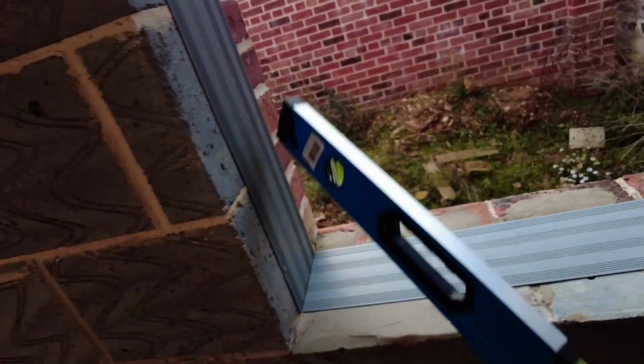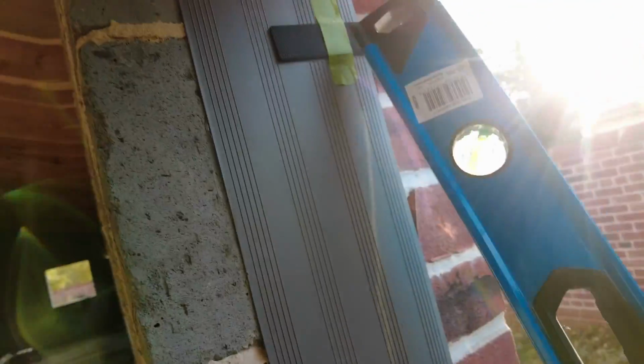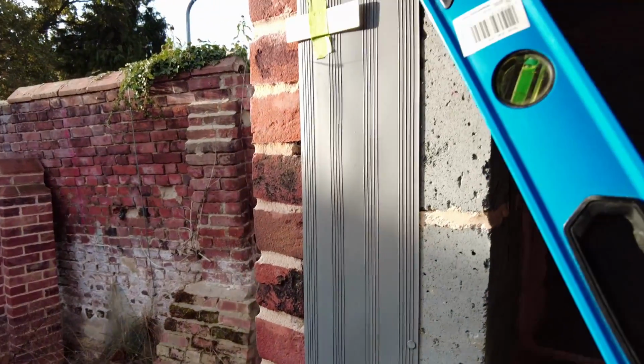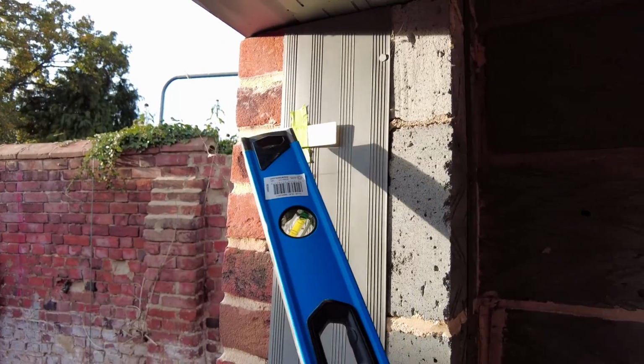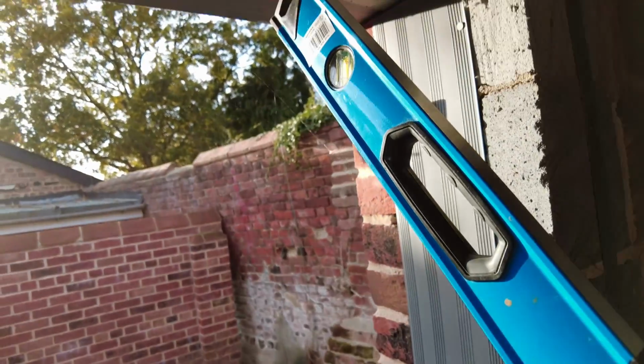I'll show you on this window what I've done. So just to double check, I put this one there, and then that one is off by 2mm. So I put that packer there, and then the other side, that one is off by 3mm. So there's that packer there, and I measured between that one and that one to make sure that my window was actually going to fit in, and the same up and down. So out of them 3 measurements that I've done, smallest one, deduct the 10mm, it still fitted in within that gap, even if I bumped it off to make it absolutely bang on level and plumb.